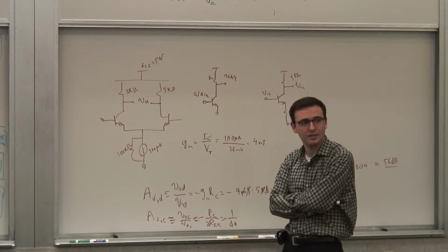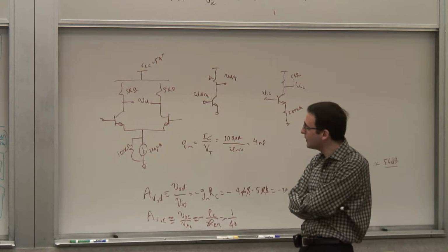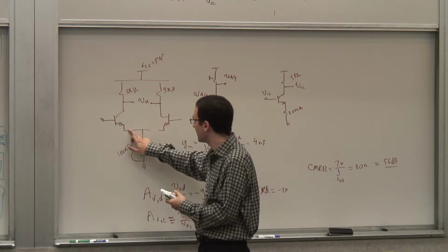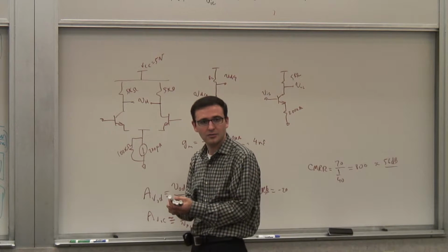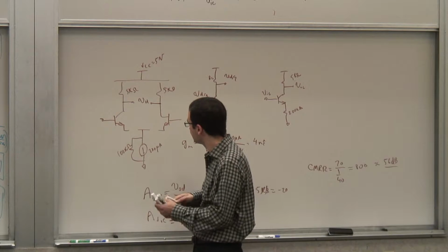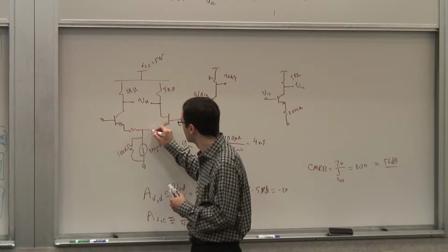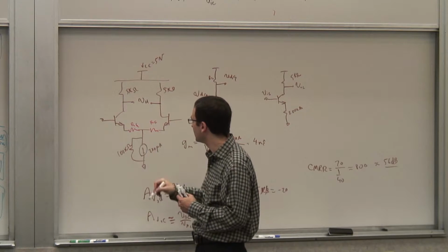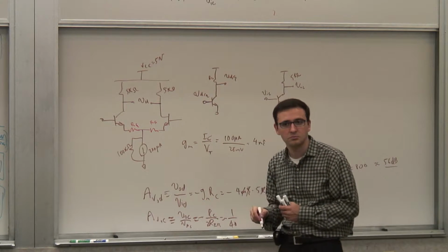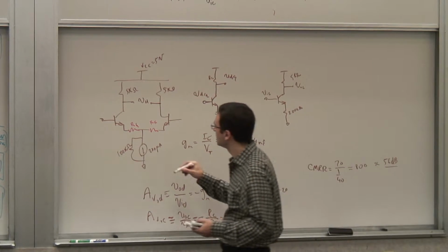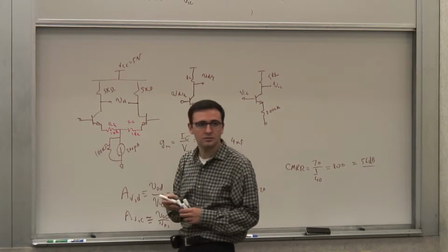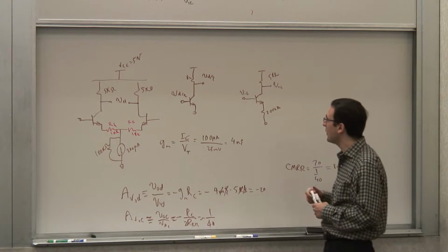Common mode, basically, right? So what else can I do? Well, we talked about this, right? So we said that if you put a resistor here and a resistor there, I can increase my linear range. Now I have to make an RE, not REE, not to be confused with REE here. Let's put a 1 kilo RE here.